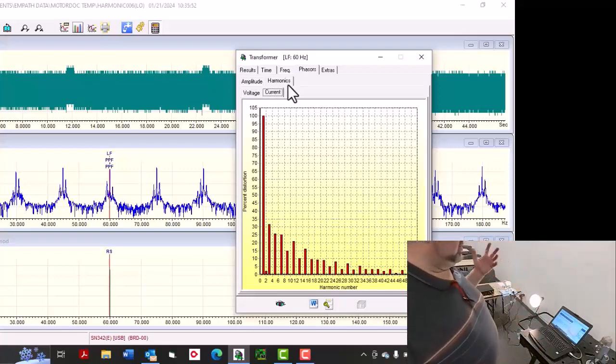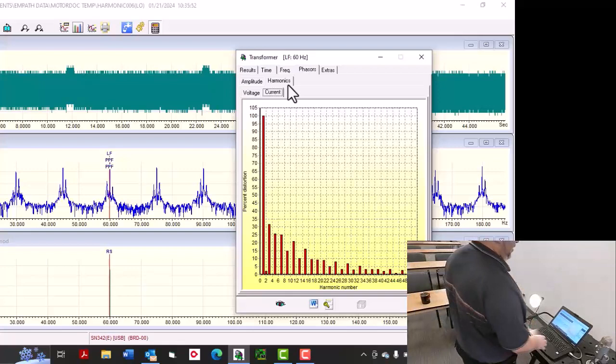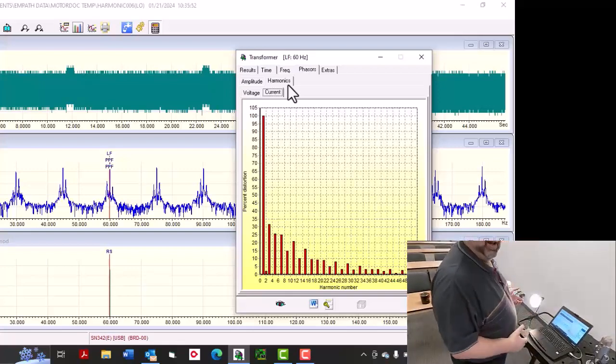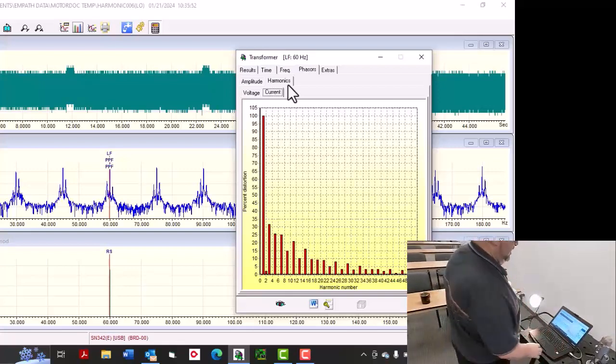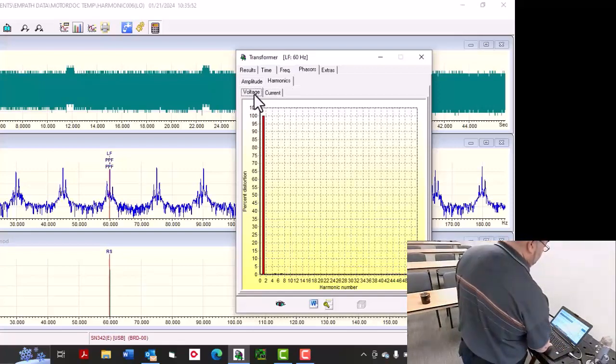So I was expecting to see some third harmonic when I approached this, because that's what we were told. But it turns out it's completely inaccurate. It's not just third harmonic going into my neutral. It's all of the frequencies. So pretty nasty there. So let's go ahead and we're going to run the last one just as we did